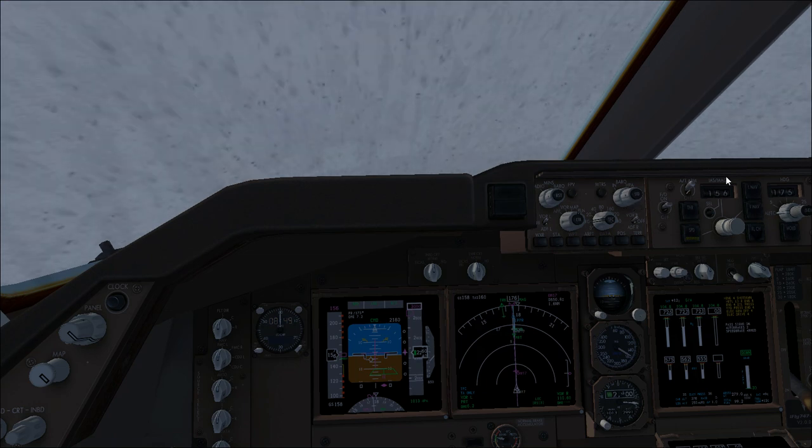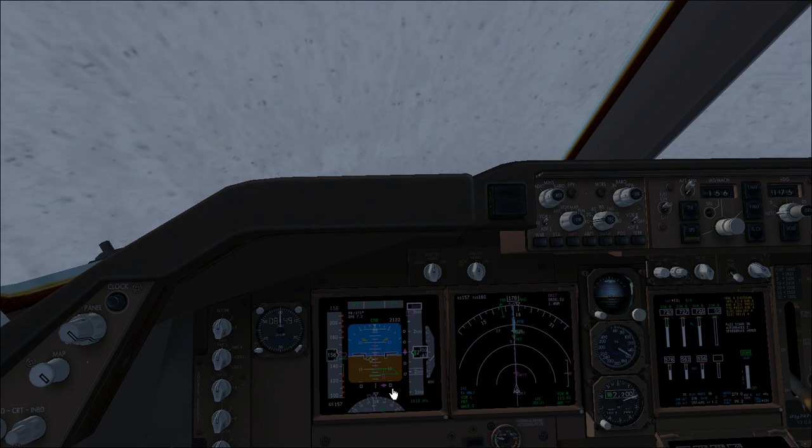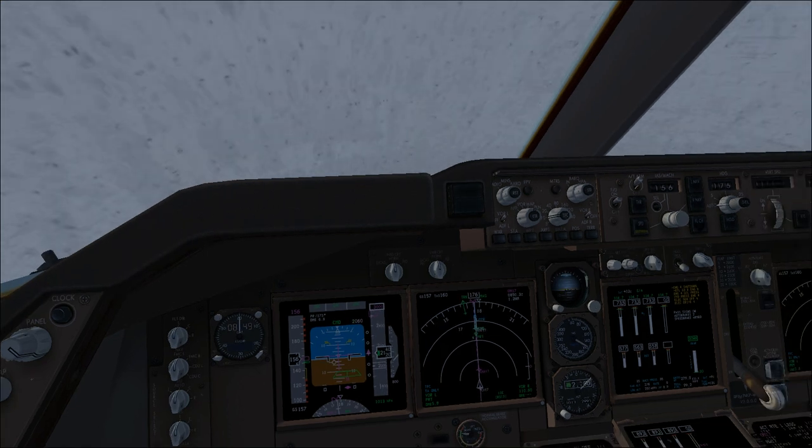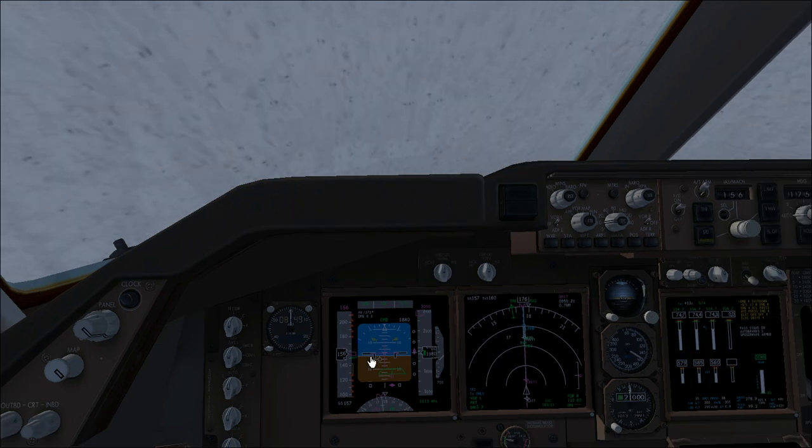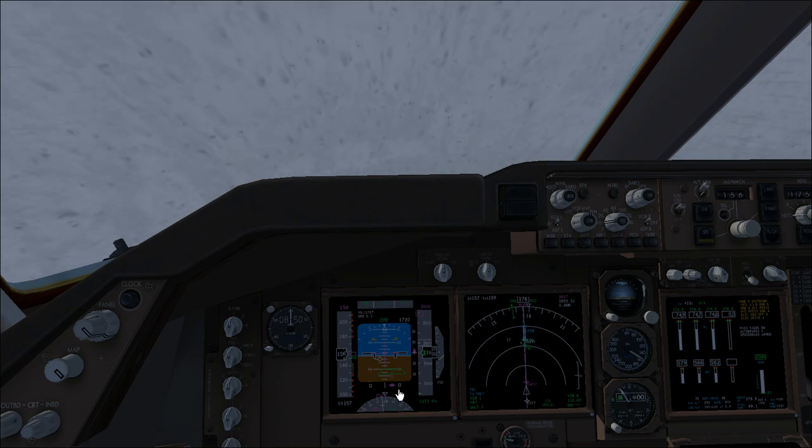We have some wind coming from the right with an engine out, so you will see the aircraft aligning at the end of the approach, but we are now approaching the runway pretty nicely. You can check command, speed, localizer, glide slope, everything set, 156, 3000 feet, and we are fully aligned on the glide slope. As you can see, the localizer is just a little bit to the right because we have an engine out and also a crosswind component, but you will see at the end of the arrival the aircraft will perform pretty well even with an engine out.